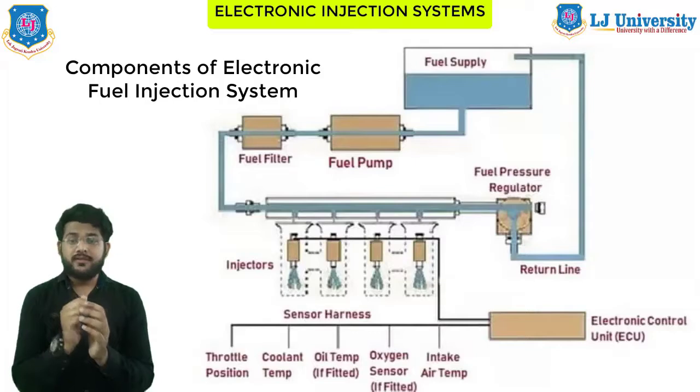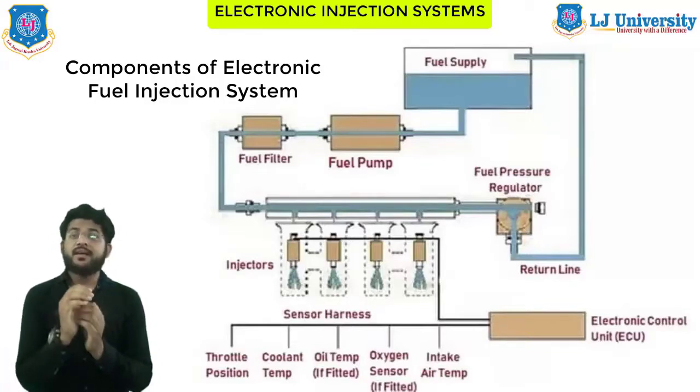Second is actuators. What are actuators? They come along with the sensors. They are the components that obtain the information from the ECU and act in the feeding system, varying the volume of fuel that the engine receives. The engine uses the following actuators: first is the fuel injector, second is the spark plug, and third is the throttle. These three are the actuators.